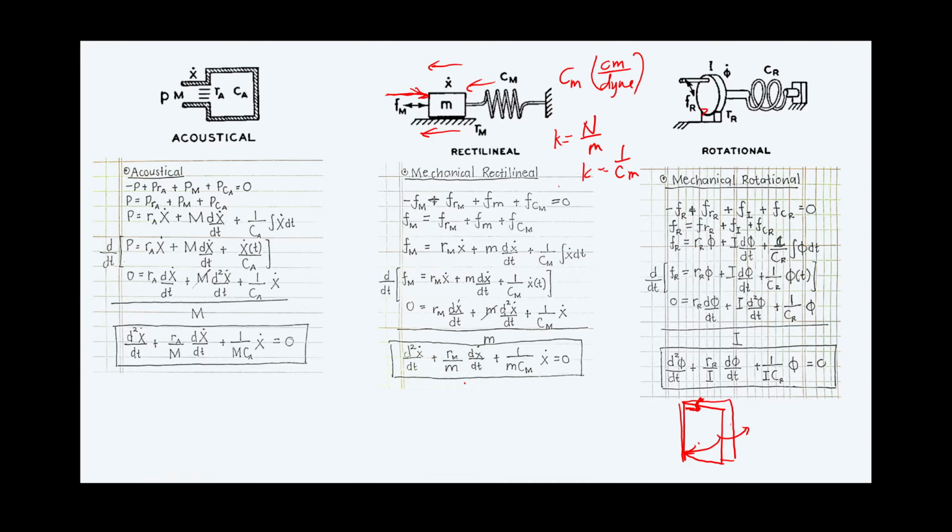And then you also have torque friction, based on the contact points of the bearing. And then you have inertia. If you have this wheel and try to exert force very fast, you notice it's very heavy, but if you force it a little more slowly, it is easier.